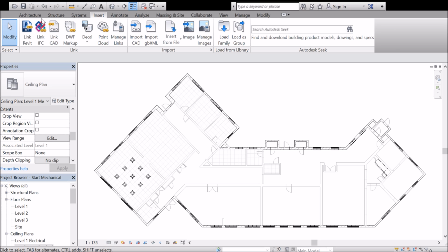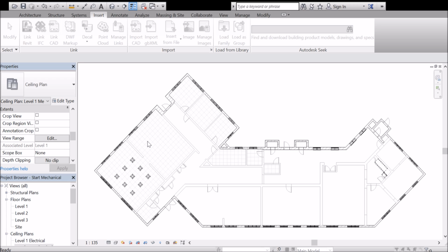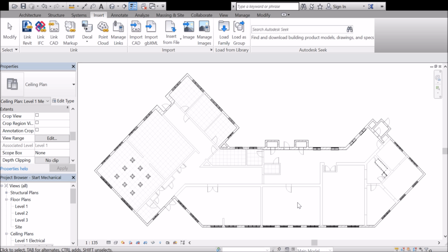First thing we're going to do is load in a bunch of families. Go to your Insert tab and hit Load Family. First off, let's load our air supplies. About everything we need is under this mechanical folder. So I'm going to go Mechanical, MEP, Airside Components, and we want air terminals. The first one we want is this supply diffuser, rectangular face, round neck, hosted. We want the hosted version, not the version right below it. So make sure you click that one. Go ahead and click open.